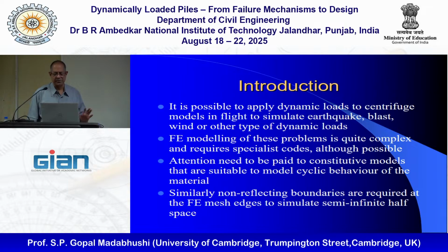FE modeling of these problems is possible, but it is quite complex, and you normally require some specialist codes. Only recently, commercial codes like FLAC 2D, FLAC 3D, Plaxis 2D, 3D became available. But until then, almost every research group had their own specialist dynamic code. ICFEP, for example, the Imperial College one. We use SWANDYNE, which is developed by Swansea, and so on. There are some advantages and disadvantages of using commercial software like Plaxis, but we'll come to that tomorrow and the day after, when you get a chance to play with the Plaxis software.